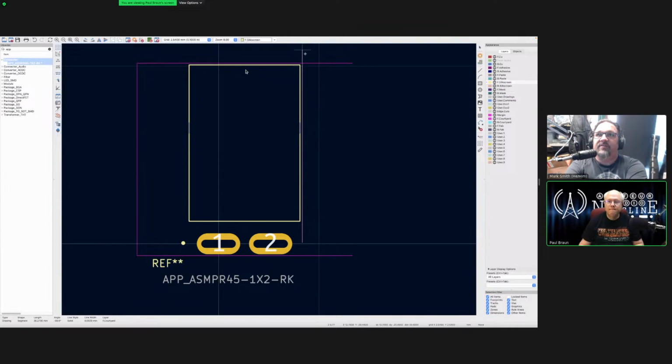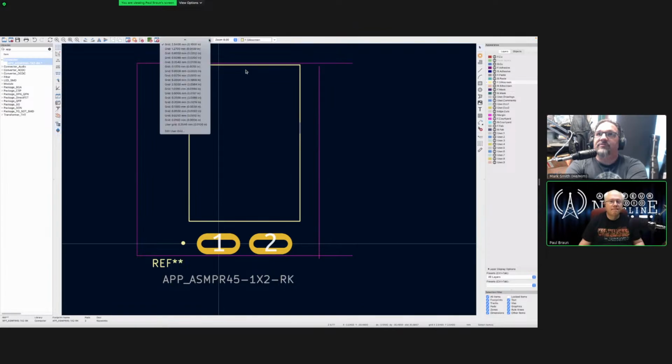And then up to the... Why is your grid so weird? I don't know. Because it's 0.1 inches. Good grief. Set your grid to like 0.025 or something. Oh, that's millimeters. Well, that's part of the problem. You know what? This probably is a metric component. Half a millimeter? 0.1 millimeter? Do 0.1. That'll be awfully precise, but it'll let us do it.